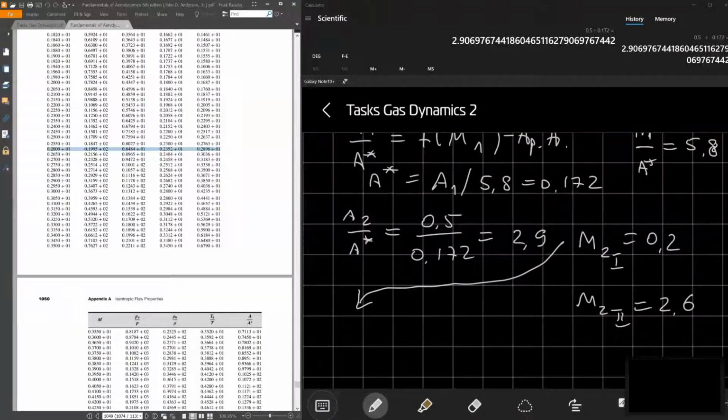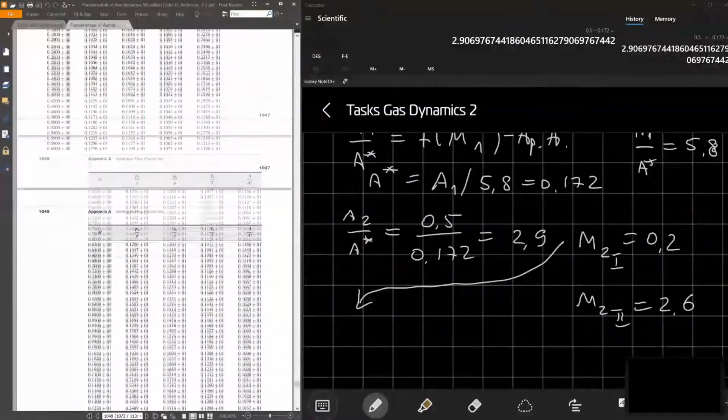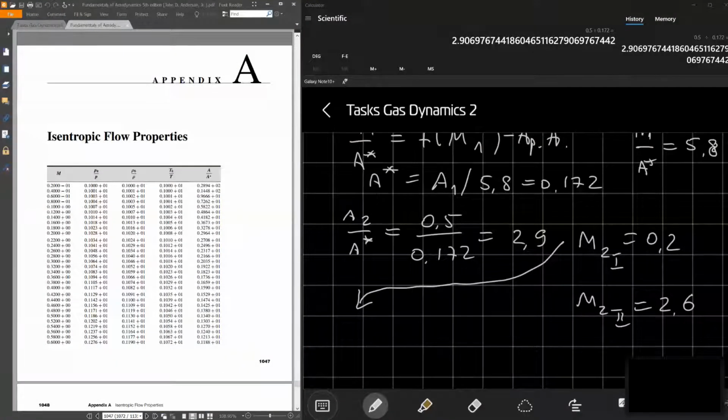First of all, we are using the isentropic relation at the initial state, at the initial Mach number we had. So Mach 0.1. At Mach 0.1, we can define the stagnation pressure. Since the static pressure is given, P0 can be found very easily here. So I will write that my P0 divided by P1 is equal to 1.007.